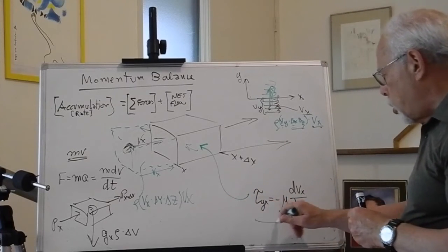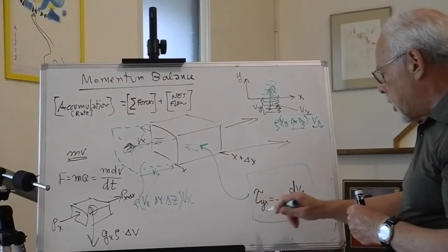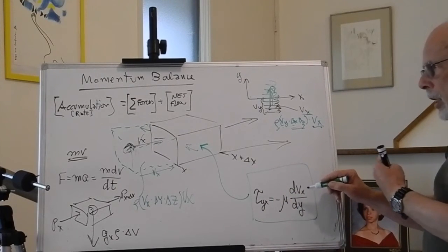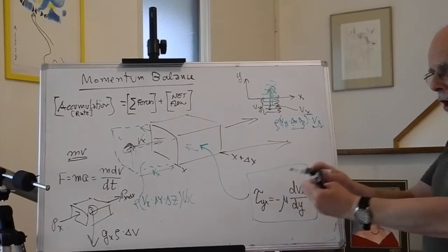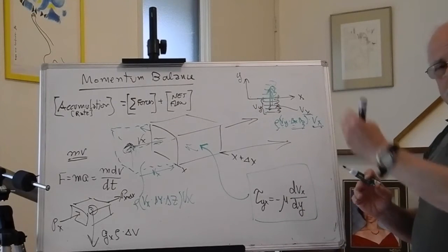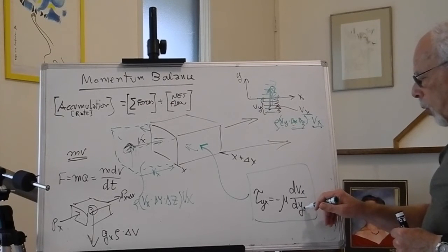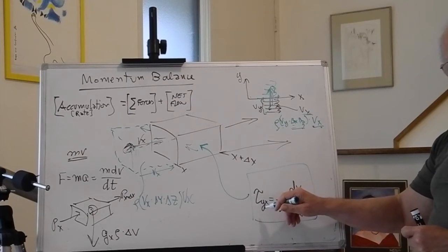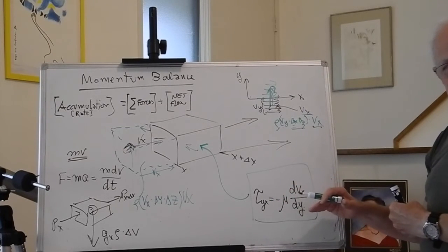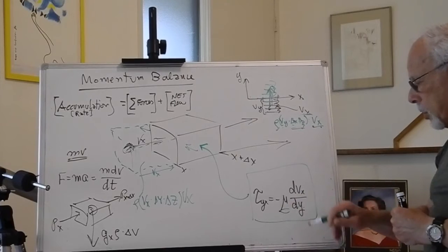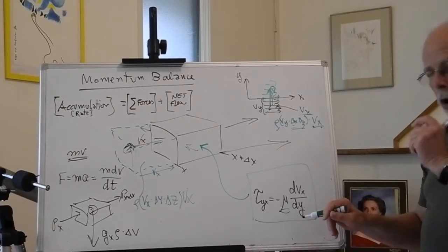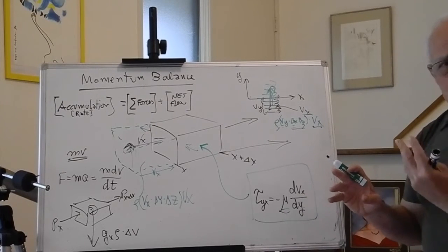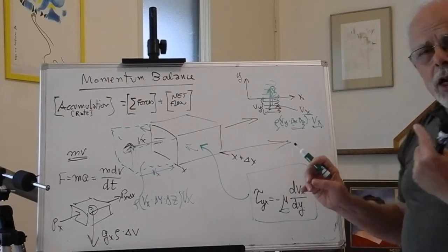This is expressed through an equation that says that the rate in which the velocity in direction x climbs up to a direction y is proportional to the force that is causing this. And mu is the viscosity or the coefficient of proportionality. So this expression represents the transfer of momentum unique to fluid,